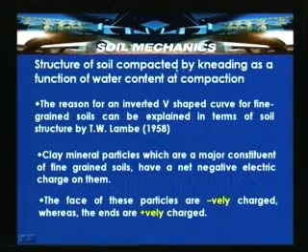We will try to look at the structure of the soil compacted by kneading as a function of the water content at compaction. We said that the reason for an inverted V-shaped curve, the compaction curve for fine grained soils, can be explained in terms of soil structure after T.W. Lambe 1958.